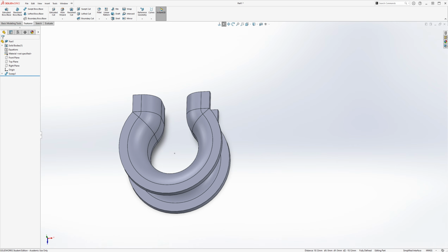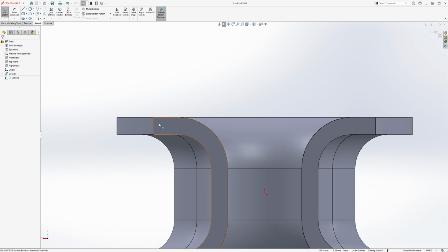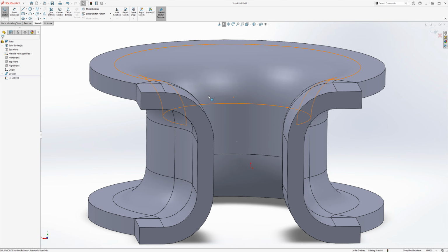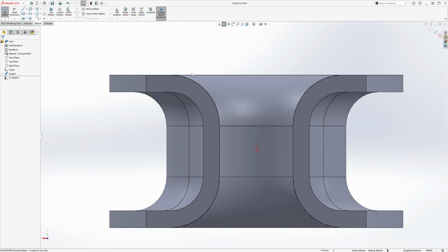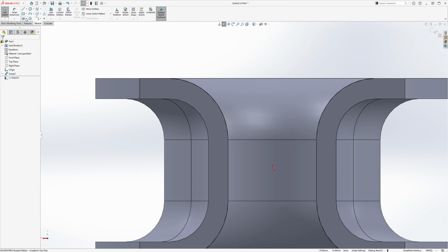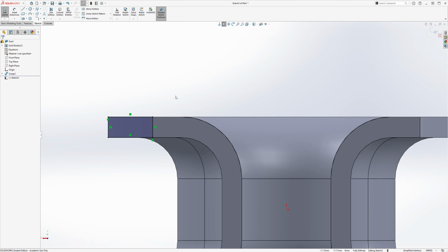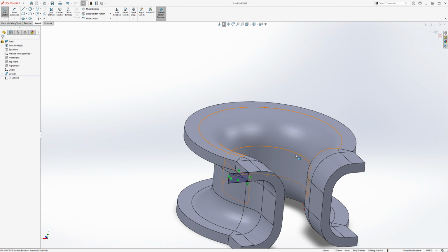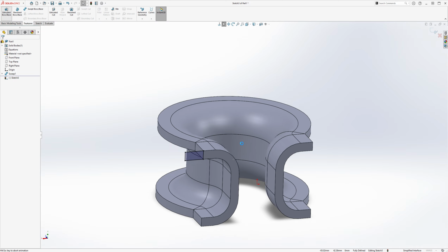And it's actually pretty nice that Solidworks gives you different color gradients for different perspectives of the part. So this will be dark gray and this will be light gray. So in the empty space in this light gray, all you need to do is just trace a rectangle. So I'll do a corner rectangle like this, and that'll cover the empty space behind the front extrusion. It'll look like this. And then you just do feature extrude by space.